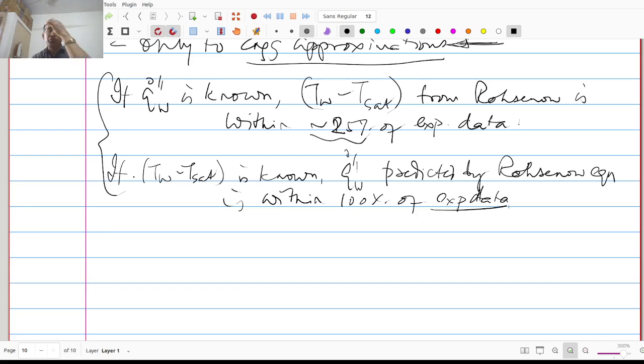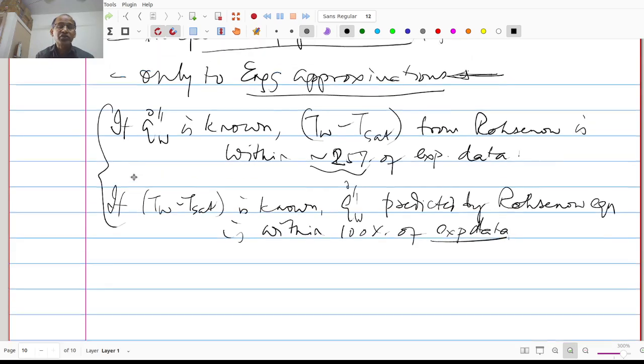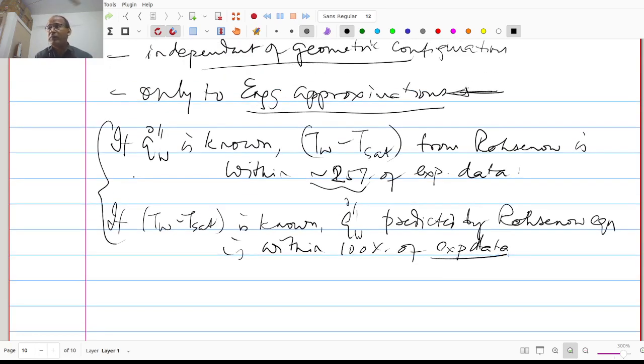So you should make sure that the flow rates of water are sufficiently high that at any given point in time no part of the tube wall would run dry. Okay, so you need to make sure that liquid water is always in contact with the tube walls, so that there is no film boiling starting to happen, and therefore no tube wall temperature that goes to excess.